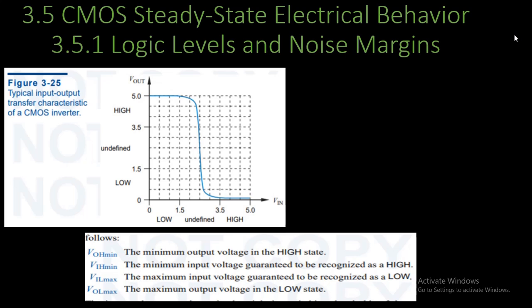It varies greatly under different conditions of power supply voltage, temperature, and output loading. The transfer characteristic may even vary depending on when the device was fabricated. For example, after months of trying to figure out why gates made on some days were good and on other days were bad, one manufacturer discovered that the bad gates were victims of airborne contamination by a particularly noxious perfume worn by one of its production line workers.